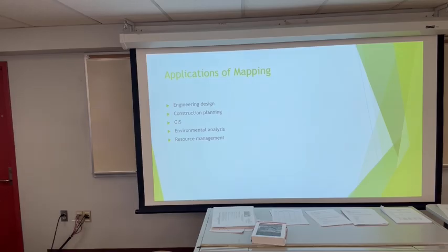Surveyors will typically go out onto an undeveloped piece of ground and create a topographic map locating the existing ground features, focusing on drainage features and any existing utilities or man-made features around there. Engineers will look at that topographic map and start designing: where are we going to put the roads? Where are we going to put the utilities? Where are we going to put the buildings, houses, whatever?